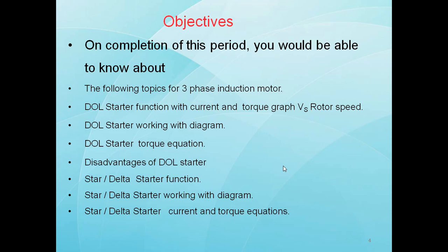Suppose the starter is not there, and you connect the motor directly. Let us see what happens. I will explain briefly as I explained in the last class. When an induction motor is directly connected to the supply system, it takes about 6 to 8 times its rated full load current at the time of starting.